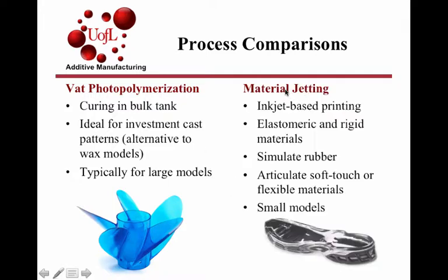In contrast, we'll look at another process called material jetting, which is based on an inkjet based printing of photopolymerizable materials. And depending upon the proportion of the reagents that are mixed together, you can access a whole range of material properties. And you can also dial in multiple material properties in different locations. Let's take a look at what are the nature of the product that comes out from both those approaches.